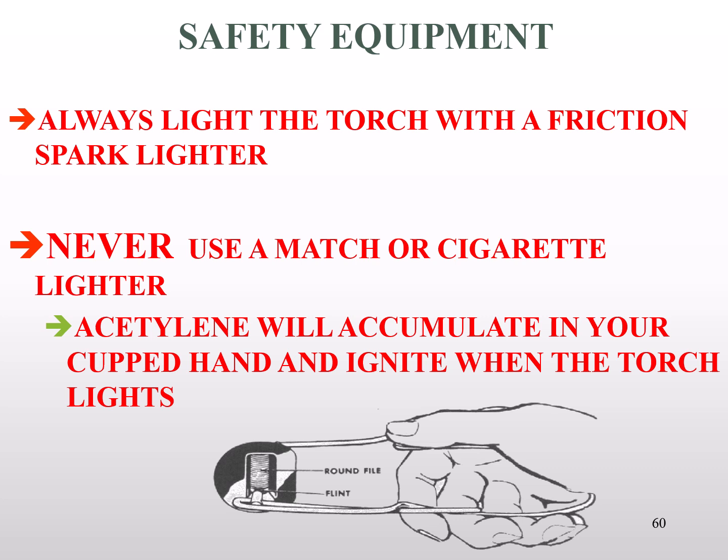Covered in our safety brief, we'll only ignite these torches using strikers. They're designed to do the job. They're the safest way to do it. We would never use matches, butane lighters, or propane torches. We always start with a striker. It's the safest and the only approved method.